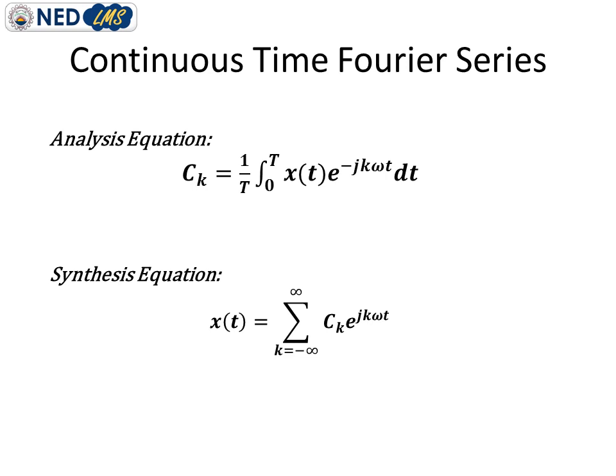You remember that in the trigonometric form we have three variables which we have to determine to actually analyze the signal, which are a0, an and bn. a0 is telling us the presence of the DC offset, an is predicting the presence of cosine waves, and bn is predicting the presence of sine waves in any complicated waveform.